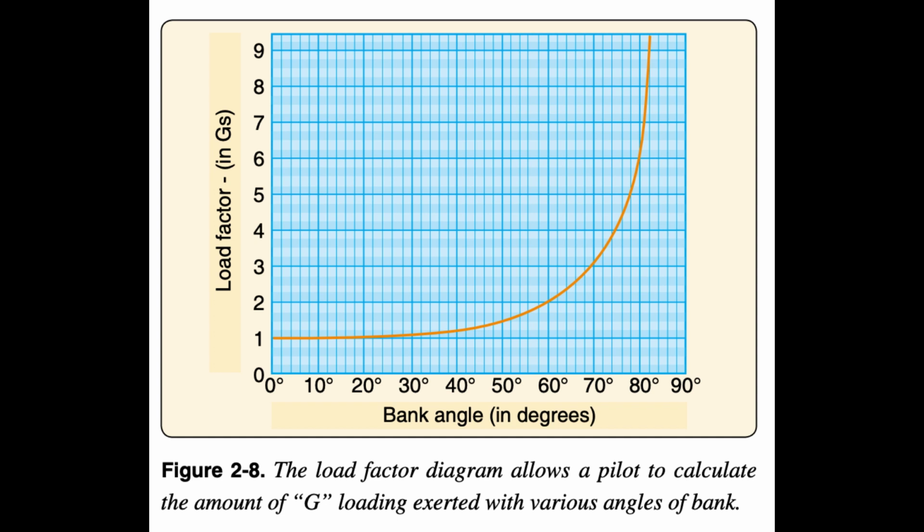Newton's first law states, every object in a state of uniform motion tends to remain in that state of motion unless an external force is applied to it. In this case, the object is the helicopter whether at a hover or on the ground, and the external force applied to it is lift, which is accomplished by increasing the pitch angle of the main rotor blades. This action forces the helicopter into a state of motion. Without it, the helicopter would either remain on the ground or at a hover.